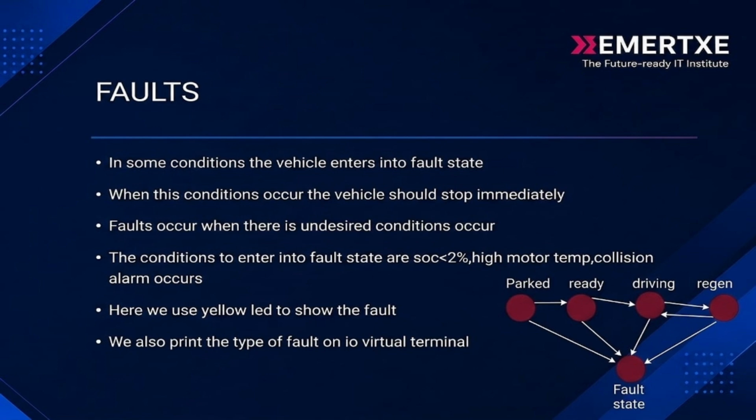Fault state. If some conditions occur, the vehicle enters into the fault state, and the vehicle should stop immediately. Fault occurs when an undesired condition occurs. The conditions to enter into the fault state are SOC less than 2%, high motor temperature, or a collision alarm.